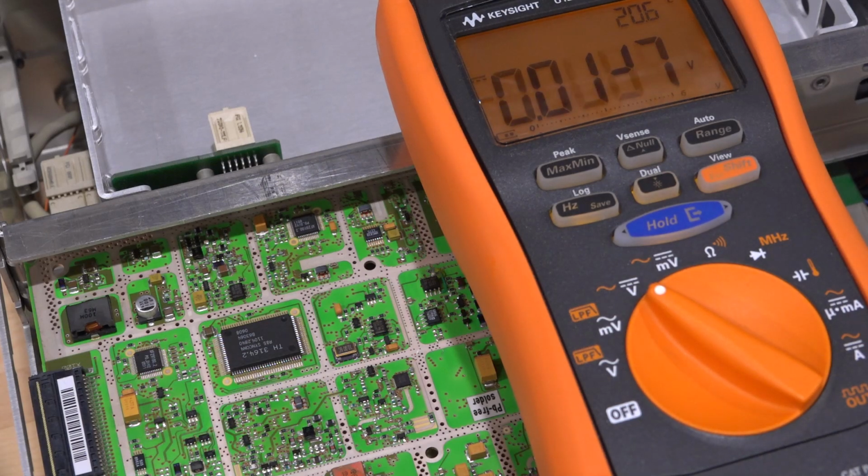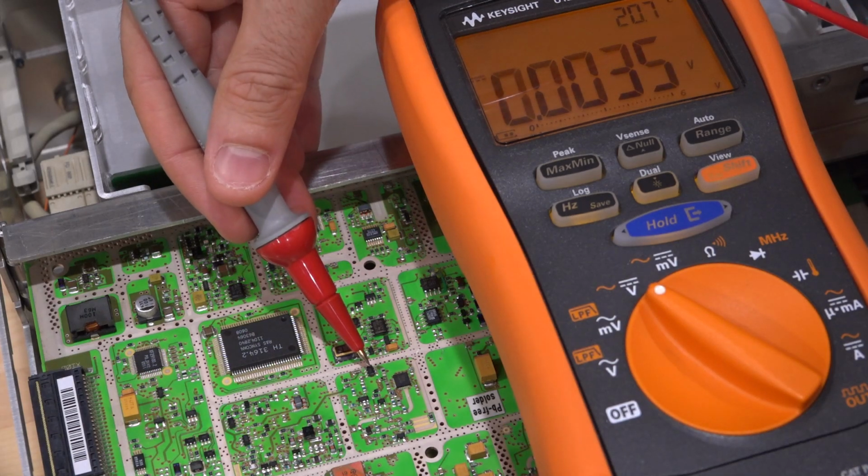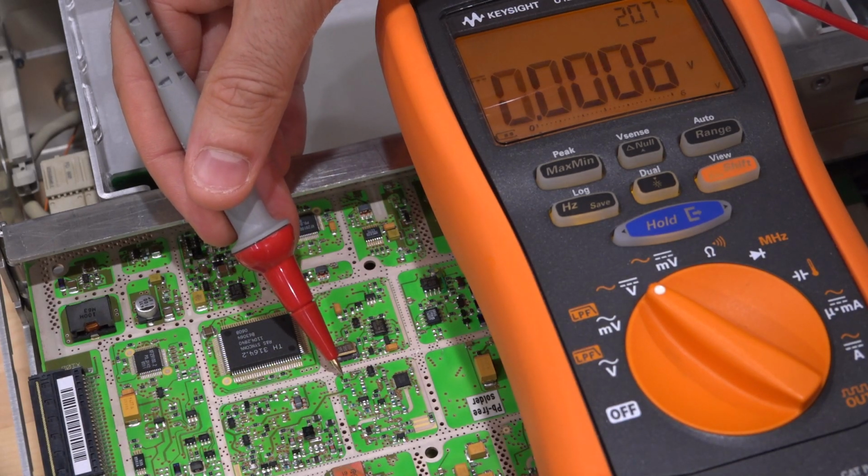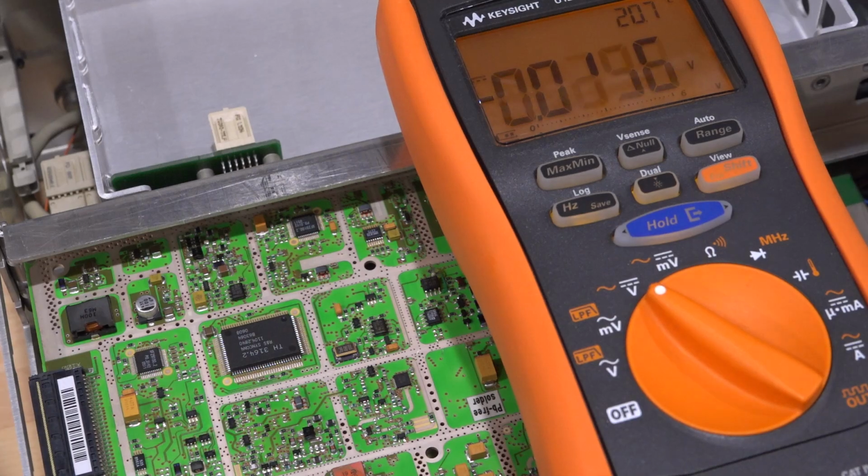So if that divide by 4 somehow becomes a short circuit, the fuse basically, the resistor, burns up and disconnects it so that the rest of the circuit doesn't get damaged, and you don't have to put a fuse in, which is quite a bit more expensive than a 1 ohm resistor and also quite a bit larger. So it may very well be that this divide by 4 is dead and that has blown out this resistor completely. So we're going to have to investigate a bit more.